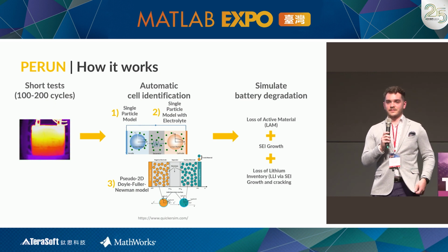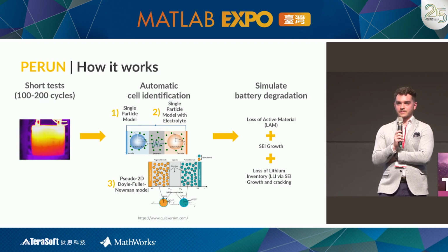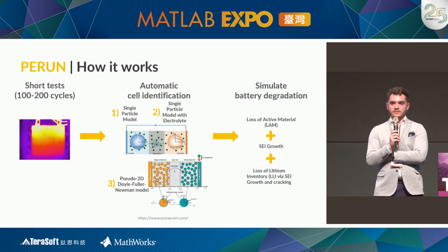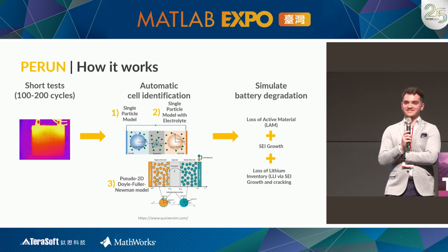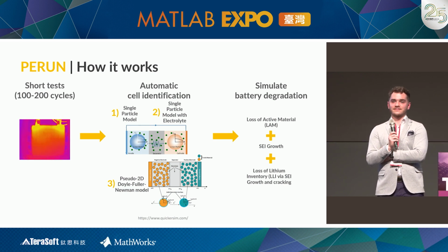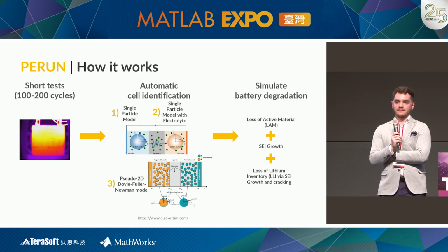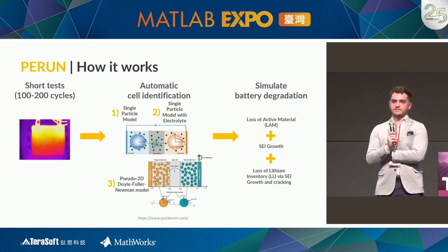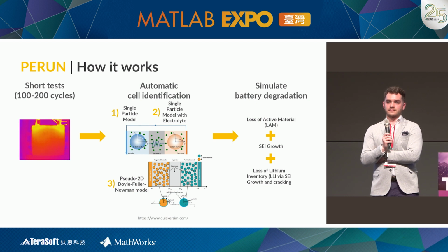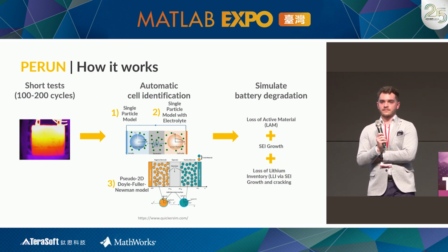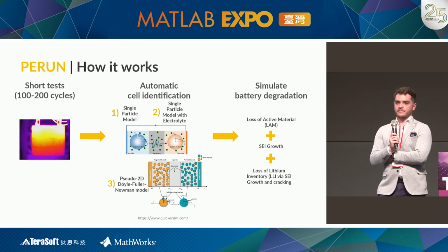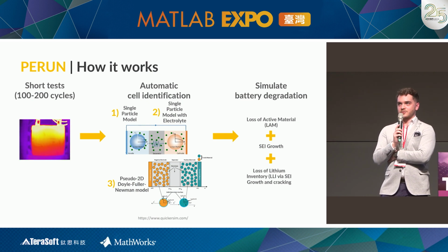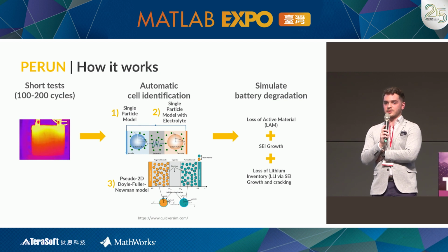From my understanding, we can use less mesh to do a rough simulation and predict which portion is the hotspot area. Then we increase the mesh at the critical area and re-simulate again to get more accurate thermal information. Well, you can do it that way. However, it still will not be as fast.